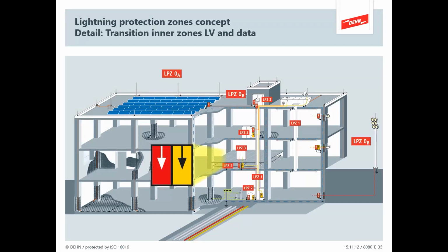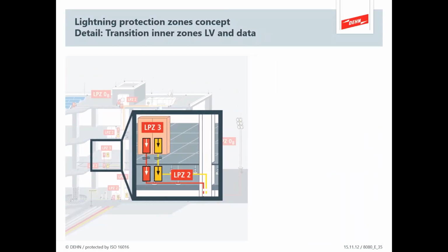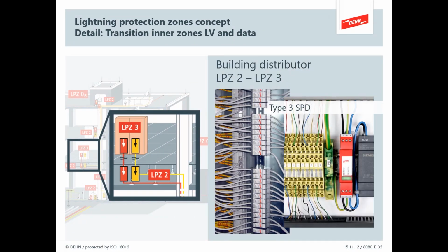And then having a further deeper look in the installation, we're now very much deeper in LPZ3, which is the PDU in the data center. We've already had some surge protection at main distribution and sub-distribution boards. This is end-of-line individual equipment protection. So we can see a small type 3 SPD on the mains, and if required, we've got some data line SPDs because we may have crossed a transition zone of LPZs within the building itself.